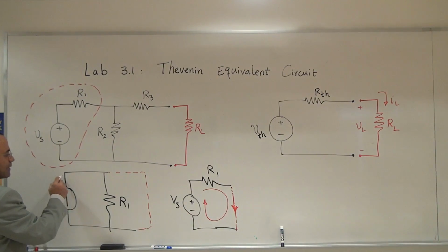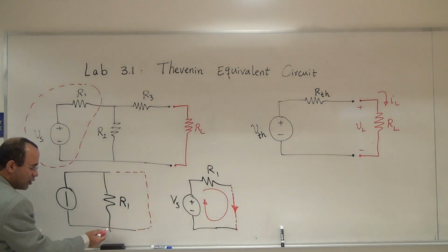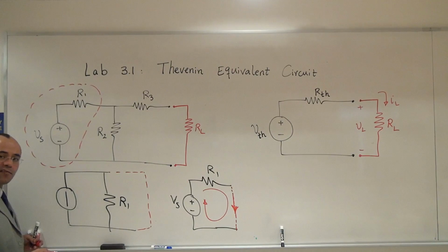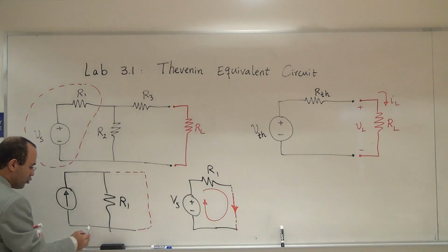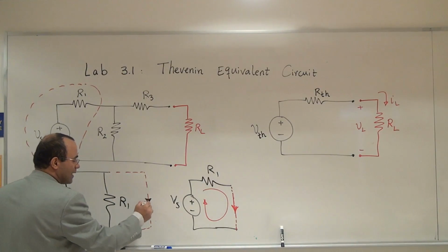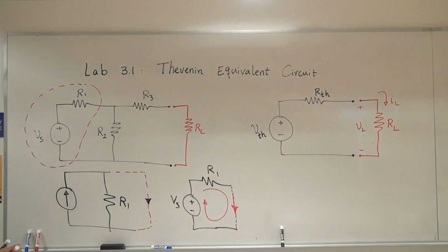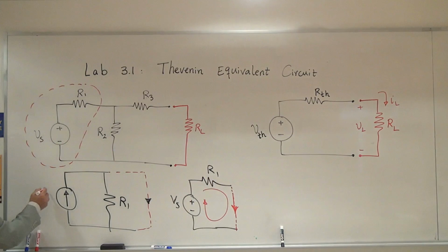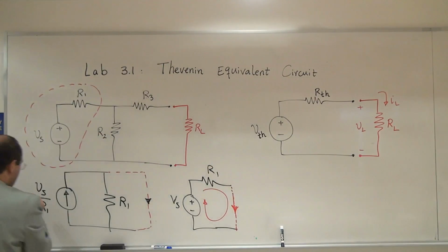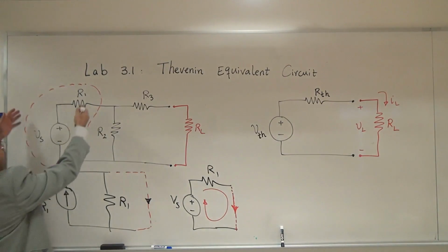Now, considering the fact that the people come in, they see resistance and they see no resistance to go to the same destination, which would be at this node, I can imagine that this direction will satisfy my criteria. The current comes in, everybody goes through the short line. That's going to be satisfying because they are matching with the short in the original design. How much is this current? Obviously you have Vs applying itself across R1, and therefore this current is going to be Vs divided by R1. Vs divided by R1, that's the current. Now I know how to replace this segment.